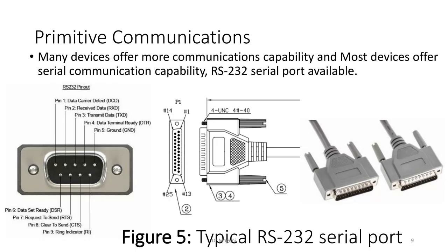So initially, this is where the communication started. If you look at the front view, it is this one here of your serial port communication. And here, this is your top view, okay? And this one here is your side view. As you can see, this one here is a 9-pin RS-232, and this one here is your 14-pin, and so on. You get different serial ports out there.